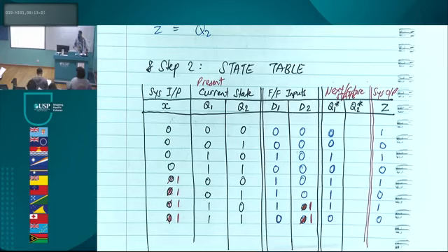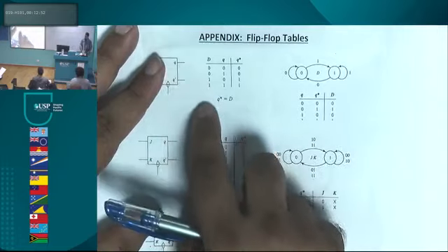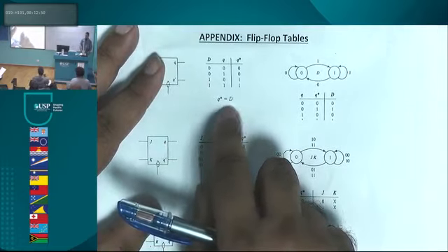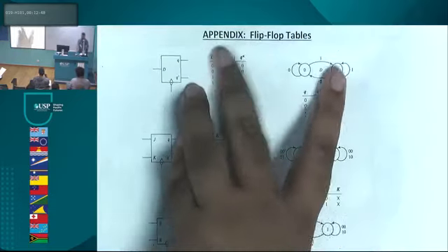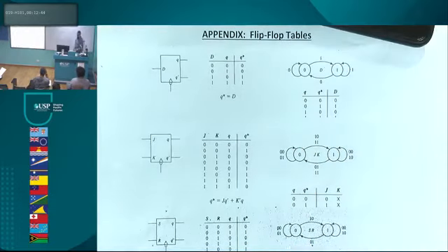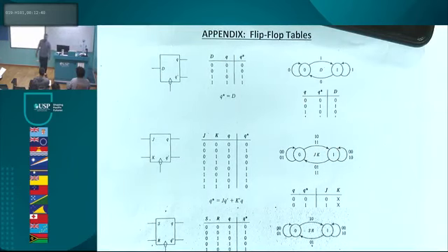Right? Okay. So I showed you how we use the table. Now, let me show you something which we wrote yesterday when we were talking about D flip-flops. Can you see here in your table, it gives you a formula. So D is one of the easiest ones that you will do. Look at the formula. What does the formula say, guys? It says that Q star is equal to D. That's the blessing about the D flip-flop. Q star is equal to D.